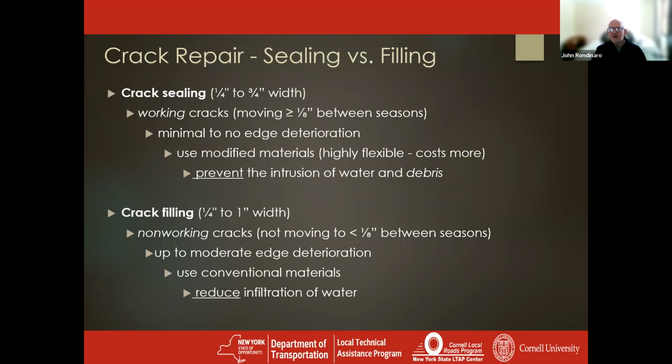You want minimal or no edge deterioration. You're going to be using a modified, engineered material, which is highly flexible to be able to deal with that moving crack. Yes, it costs more, but it's the only thing that's going to work in that case. And the key here is you're preventing the intrusion of water and debris. The reason you're concerned as much about debris is the crack is wide open in the middle of winter.